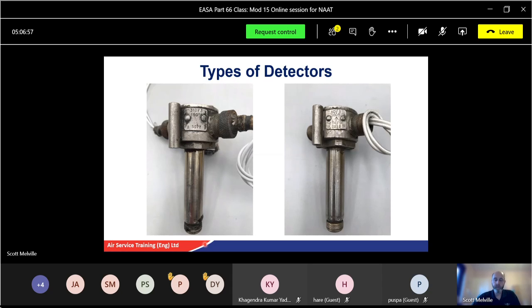The part number is the only positive way of identifying the item. They might come as a set for different operating temperatures, so the only way is to check the part number on it. For different areas, they'll have different settings. So again, although it looks the same, make sure you fit the right one.